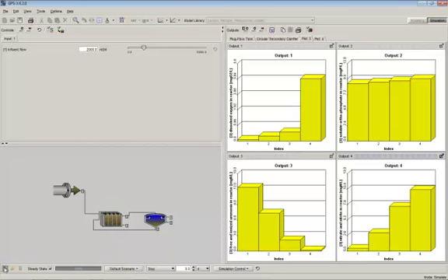This is the kind of output that you'd construct if you were doing a typical nutrient removal investigation with a model. And if I rerun that simulation here, you can see that this is the front end of the plug flow tank, and this is the back end, and our oxygen is sort of depleted at the front, and it's higher, almost 4 milligrams per liter at the back end. So these are the ways that you investigate how that plant is going to perform, and it's going to predict what the concentrations are. Just to summarize, even though we've got some depressed oxygen at the front end of the tank, we are getting pretty much full nitrification here. This is the ammonia going down as it goes through the length of the tank, and we're generating some nitrate, of course. And we're not really doing any significant bio-P removal in this particular case.